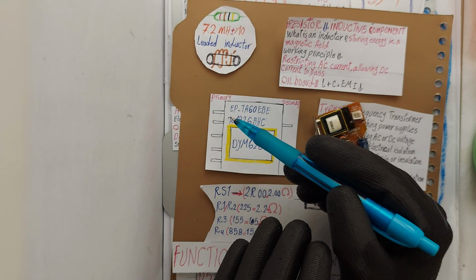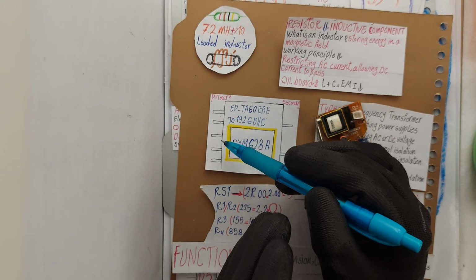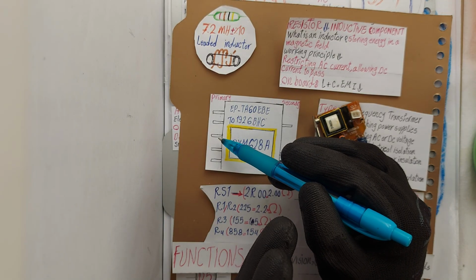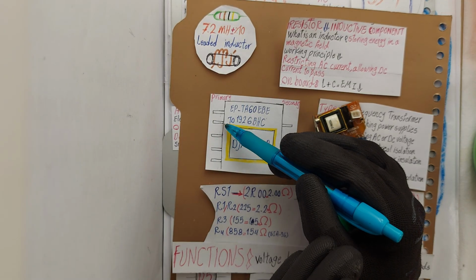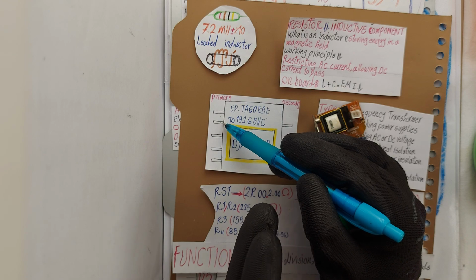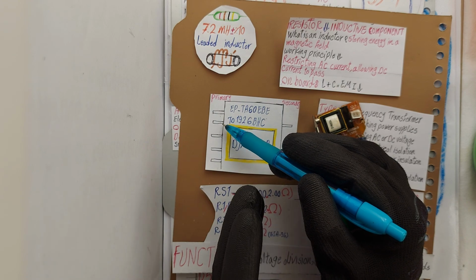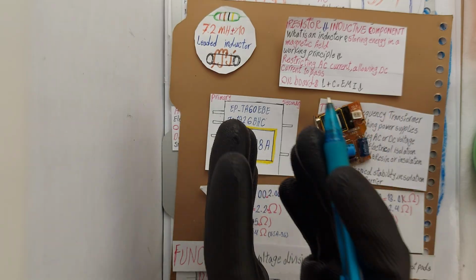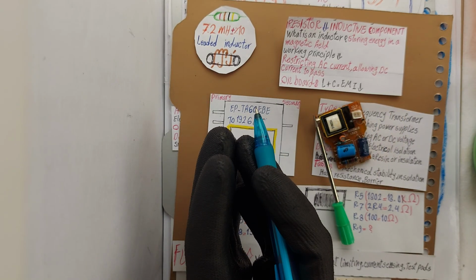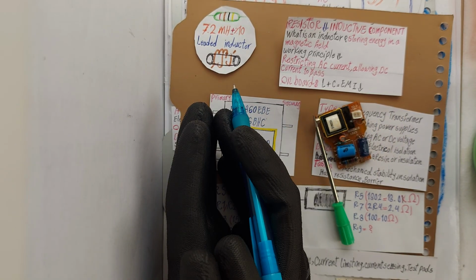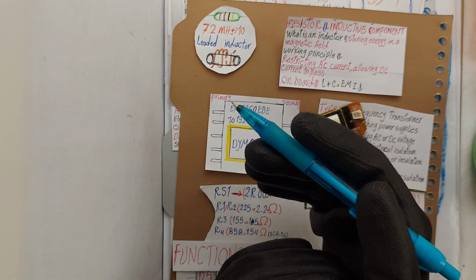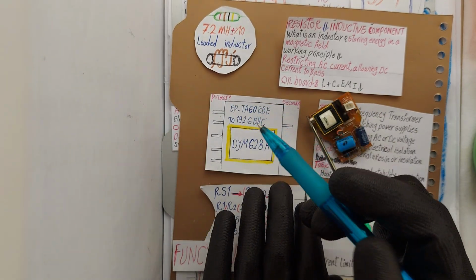The second pin connects to the transistor collector in our circuit with the OB25133 IC. This pin connects to the internal switch transistor pin in the IC. In other words, when the IC turns on, its internal switch current flows through DC bus to transformer, then transistor and ground. This stores energy in the transformer's core.